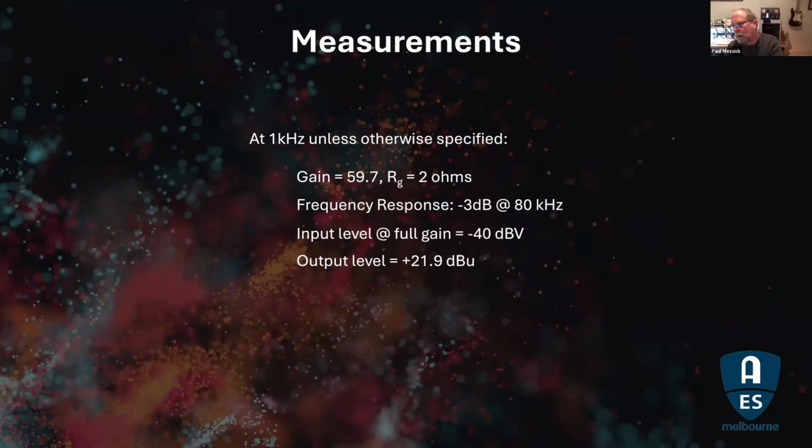We're going to take RG out and we're going to have a 0 dB gain. So it's a line input. And that's when that 1K starts to kick in. And I actually did breadboard this with 2K just to double check my sanity.